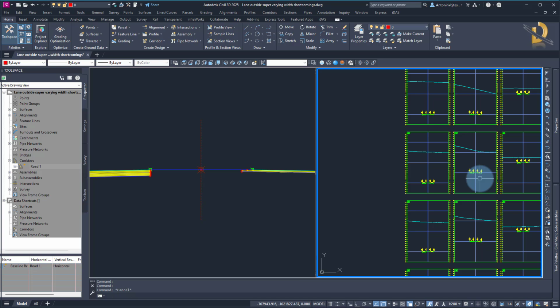And what I wanted to show you with this exercise is that some subassemblies do not have all the required properties that you would expect from that specific subassembly. So keep that in mind, that you might sometimes hit the wall. And in those cases, if you don't find a solution with the default subassemblies, the only option is to use Subassembly Composer or to develop a subassembly programmatically.